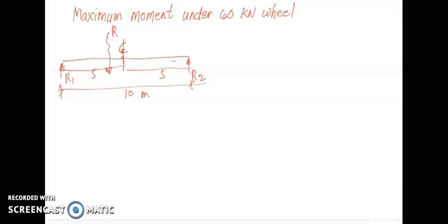So if this is our center line, so this is our resultant, our R. So this will be our 60 kilonewton. So this distance actually is 2. So therefore this is 1. And the distance, since this is 5, so the distance from the resultant towards the R1 is 4. So this is actually equal to 4. And we still have our 40 kilonewton. So this distance is 3 meters. So basically, this is also equivalent to 4 meters.